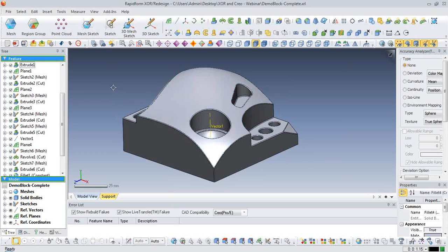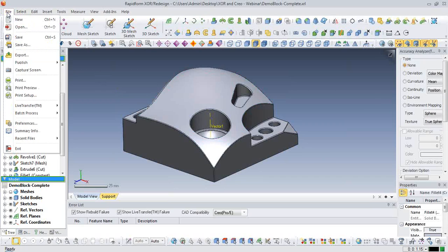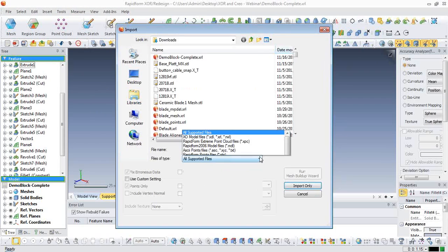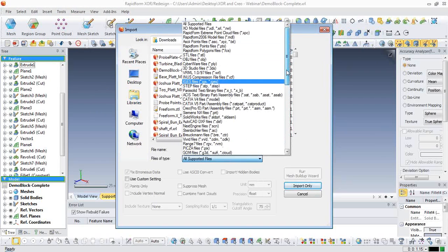So can the software read in CAD files? So in terms of importing files, take a look at that. You can see that we support a variety of files, but specifically for CAD, we're able to import your IGES, your STEPs, your Parasolids, and we are able to import native CAD files, SolidWorks, Pro-E, or CATIA, but when that's brought in, that's bringing in just the model information, not the feature tree. We're not able to import the feature tree because it's pretty complicated. If we were able to, that'd be amazing. But unfortunately, the technology isn't quite there yet, at least in development. But we are able to bring in native CAD files as well if need be.